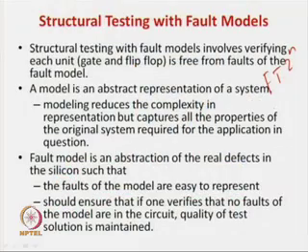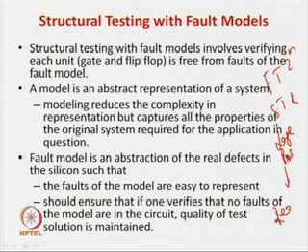So the large number of input patterns we solved using structural testing. Then using the internal registers we solved the problem of a large number of pinouts. Initially with functional test it is 2 to the power n, then with structural test we brought it down to k, then we had large pinouts, which we solved using the registers. So now we are in a position where we have a huge number of registers. This is our flow.